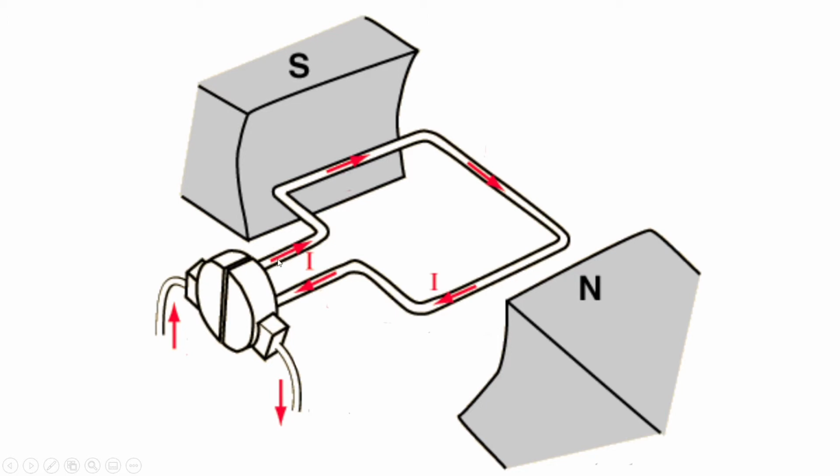It shows that one end of this loop, or one end of this coil, is going to touch a connector allowing current to flow in, and the other end touches the commutator, and this is the brush that brushes up against the commutator, allowing the current to flow out. And basically what's going to happen when you connect these two wires to a supply of electricity, current will flow in around the coil, and as we now know, that creates a magnetic field.